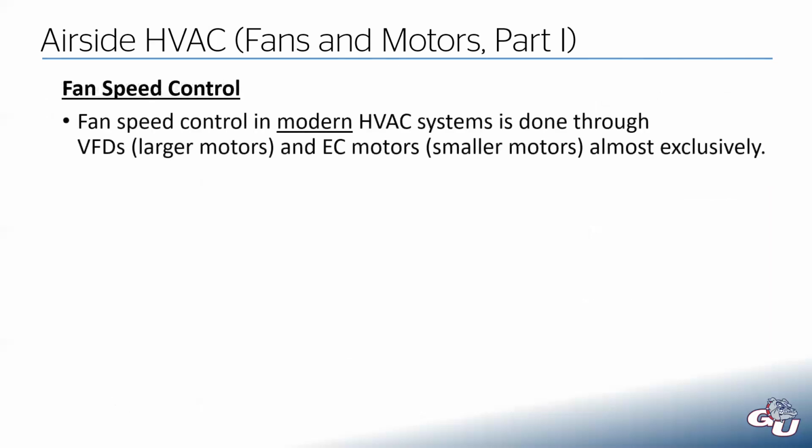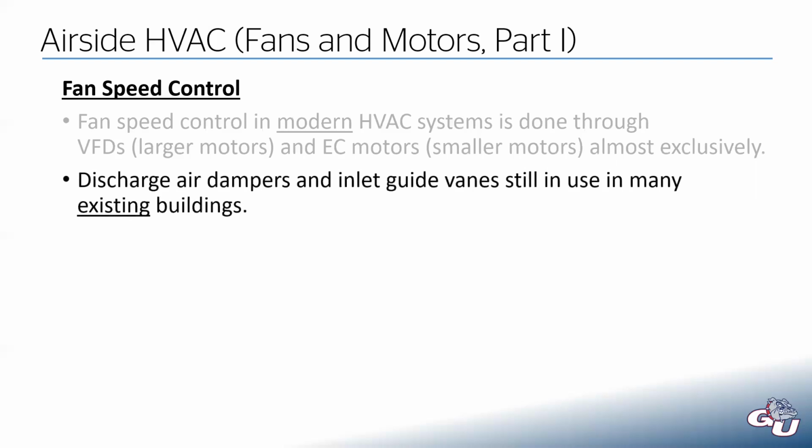If we're talking about modern HVAC systems, it's pretty much done exclusively through VFDs or EC motors. It just depends on what size of motor you're dealing with. Discharge air dampers, inlet guide vanes, we don't really see these on new systems. I've never designed a system where we've installed new discharge air dampers or inlet guide vanes, but I've been involved on a lot of projects where we've taken them out and converted the system to say a VFD system.